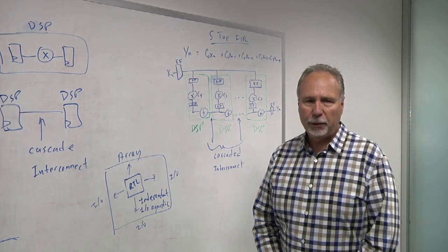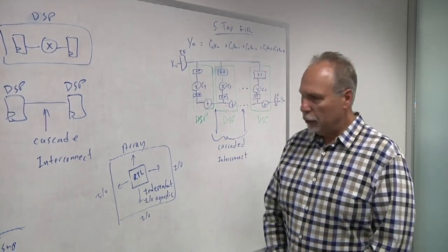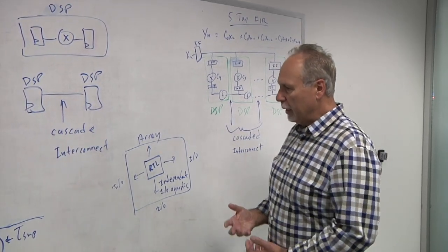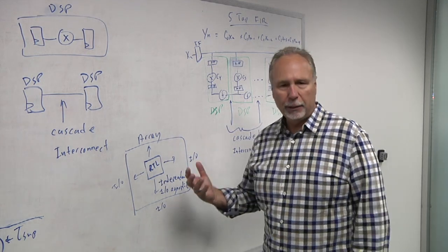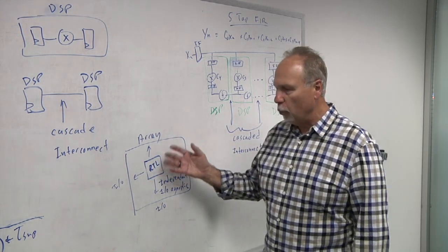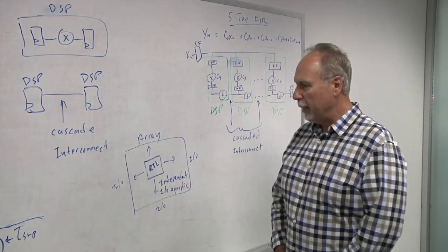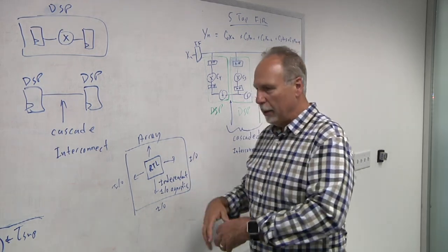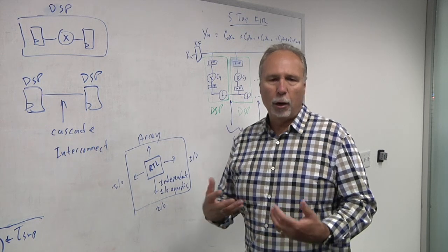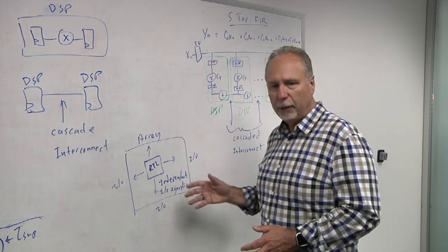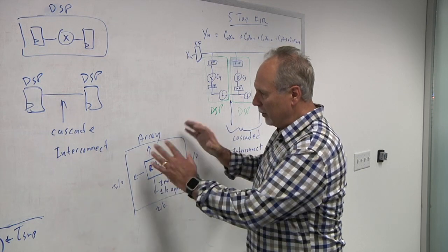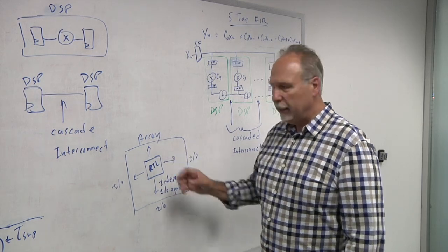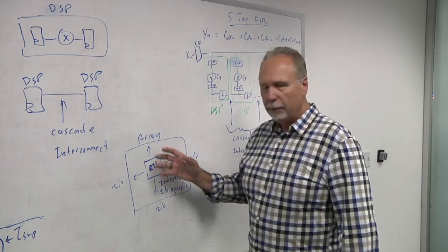So how do you test this and make sure it's really going to work as you think it's going to? One of the things that is important when you test out RTL in an embedded FPGA is to see how fast it works and how to write RTL that is I/O agnostic, or independent of where you place that RTL in an array. Unlike an ASIC, where if you have RTL you could just time the RTL from the input of the function to the output, an embedded FPGA is a physical array, and the IOs are physically located, so you want to write the RTL in a way that is independent of the IOs.